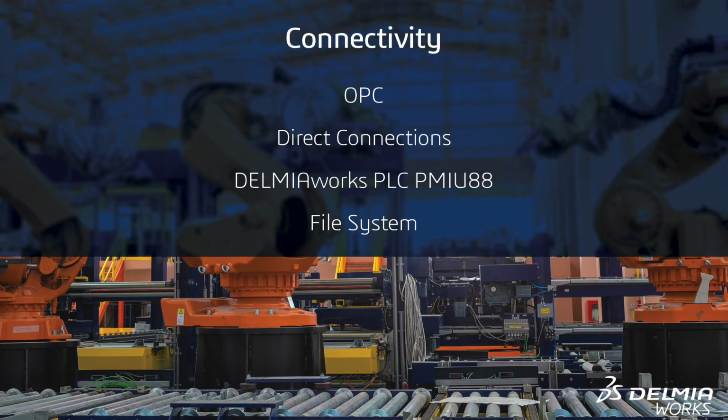The OPC server is a software program that converts the hardware communication protocol used by a PLC into the OPC protocol. Most new industrial systems are OPC client-server compliant. Legacy PLC and field components can be made to be OPC compliant when bridged and connected using their legacy drivers and protocols to an OPC server.